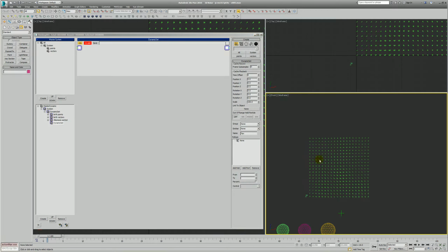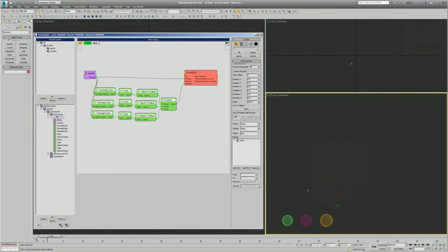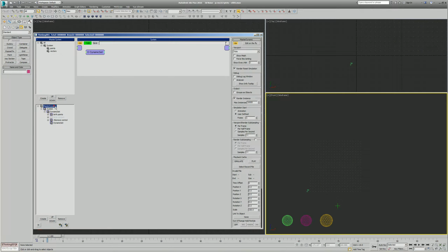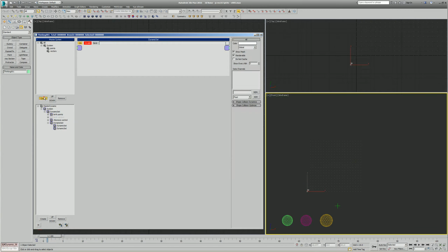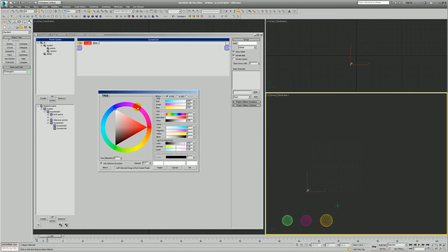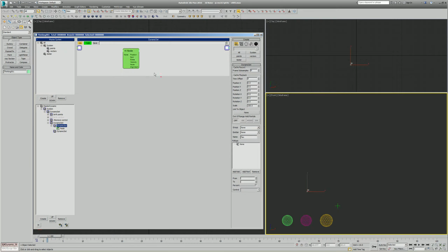And so go ahead and just copy this whole block, turn off the birth vectors, turn edit on the fly back on, and now we're going to birth a new particle. We'll call this tester, a nice bright purple. Set it as drops, and let's use the node to control where it's born.